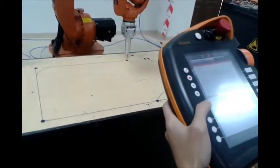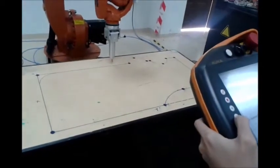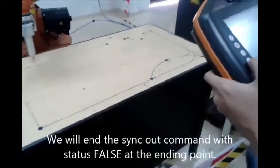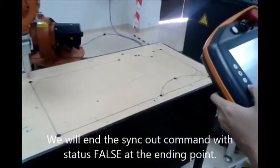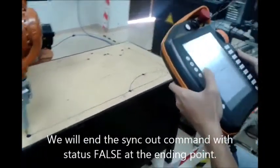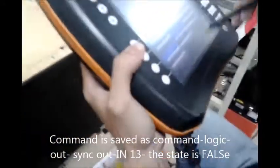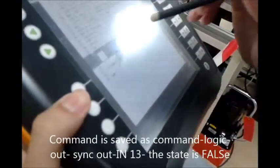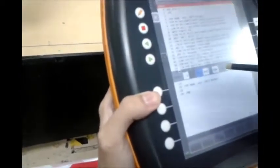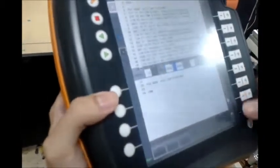Okay, so then we will run the program, run the robot. We need to find another point to end, meaning to force this logic function. So we decided to make it at the beginning point, also the end point here. It's the same here: we use command, then logic out, sing out, same as just now it is 13, and the state is false. We also use start over here, and then command OK.